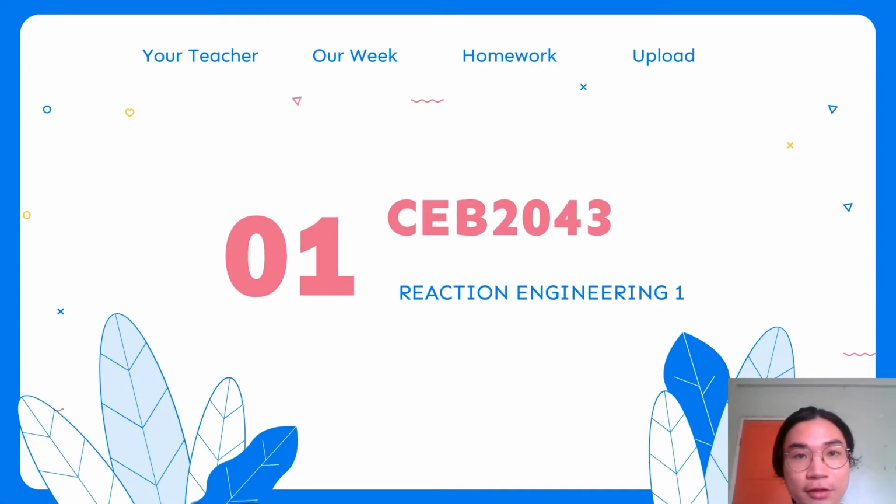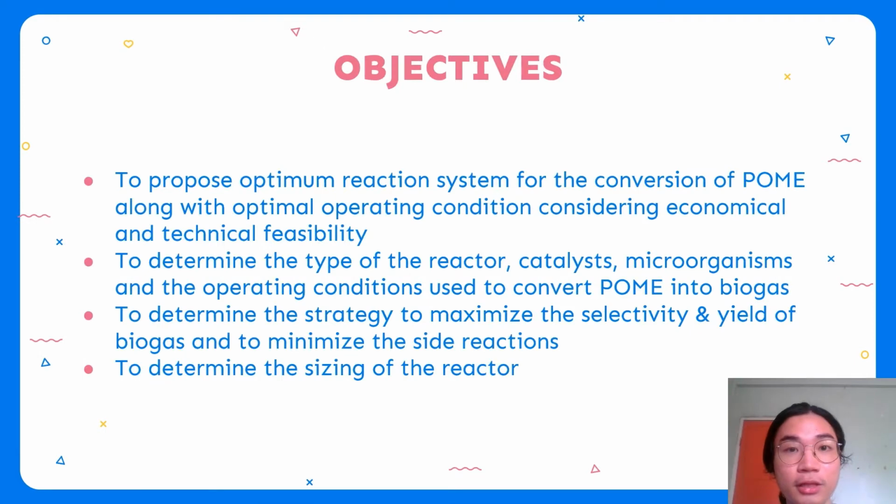This is the summary of what we have done for Reaction Engineering 1 part. The objectives of Reaction Engineering 1 part is to propose optimum reaction system for the conversion of formic acid along with optimal operating condition considering economical and technical feasibility, to determine the type of the reactor, catalyst, microorganisms, and the operating conditions used to convert formic acid to biogas, and also to determine the strategy to maximize the selectivity and yield of biogas and to minimize the side reaction. Last but not least is to determine the sizing of the reactor.